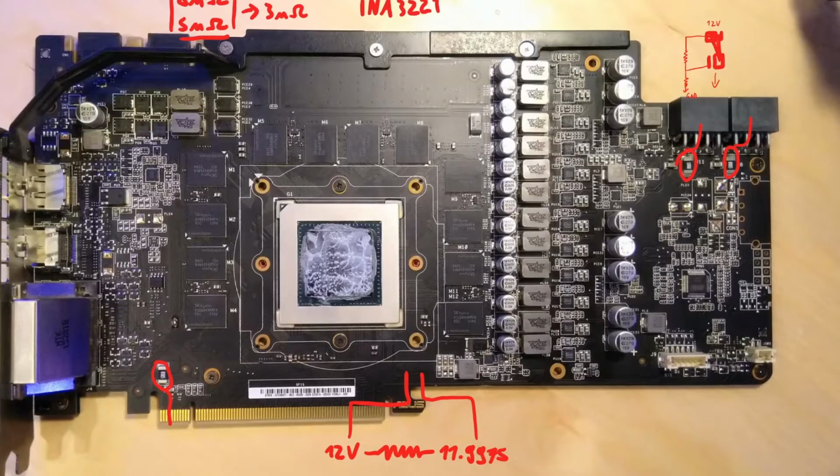That's like the easiest hardware modification that you can do, and it's kinda also the only one that works on the 20 series, because the other one... Yeah, I don't think someone has gotten it to work on a 20 series card. It does work on 10 and older though, or partly on 10, because there's a thing that can happen. Yeah, so soldering an 8 milliohm shunt on top of the 5 milliohm ones is one method to extend the power limit, or to lower the value the INA3221 reads.